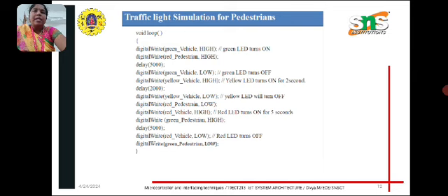The Arduino has several digital input and output pins labeled D0, D1, D2, etc. These pins can be configured as either input or output. When used as input, these pins can read the state of a digital sensor, either high or low. When used as an output, they can send signals to a controller or other digital devices.